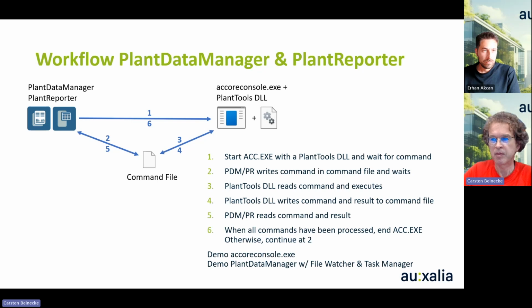You don't see it. With this AC Core Console comes a DLL we developed, and this DLL is listening for commands. The exchange between Plant Data Manager and Plant Reporter on one side and Plant 3D on the other side goes through a command file. Plant Data Manager starts it and writes a command in the command file.